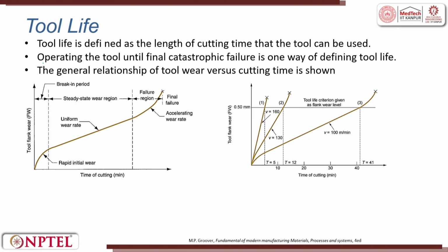So, if we plot, the tool life is very important, like finding out the tool cutting power. So, here we try to find out the tool life. The tool life is a gradual phenomenon. Tool life means finding out the tool wear. Tool wear is a gradual phenomenon. I divide the plot into 3. The initial one is called running-in wear, then uniform wear, then the failure region or sudden failure region. So, it is divided into 3 zones: zone 1, zone 2 and zone 3.